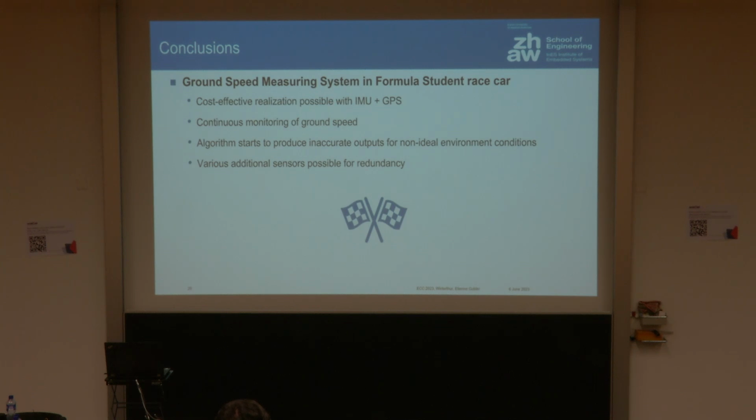The IMU alone does work, but we can significantly improve the accuracy if we get a fixed true signal from the GPS at a lower frequency. So that's why we combine this. The GPS is very accurate, but we don't get that high of a frequency, which we can compensate with the IMU. That's why we did this.